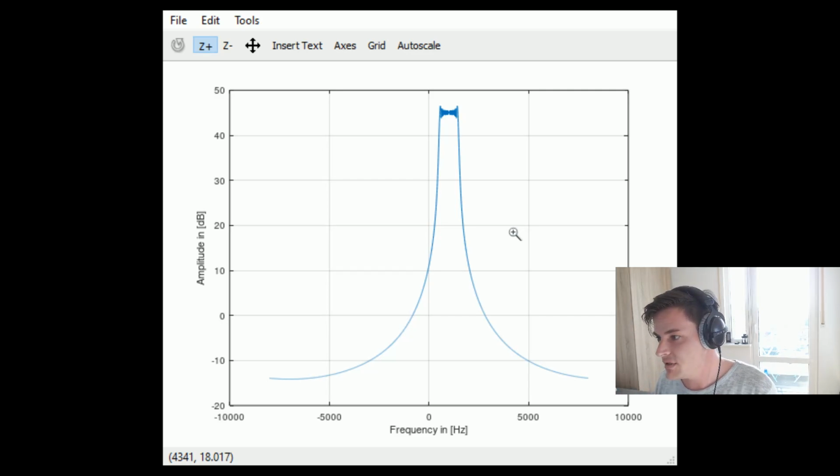If you want, for example, to calculate the frequency response of an audio device, then you can feed a chirp into the device. The chirp is increasing its frequency linearly, and you can sample the output. Then you can see the frequency behavior of your device over frequency. So it's a very good measurement signal.